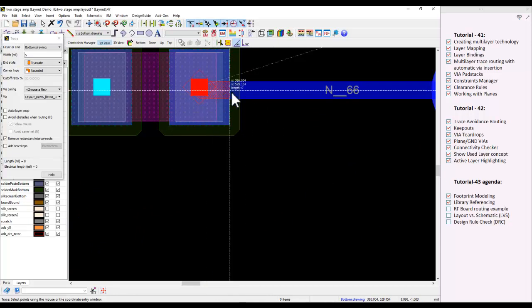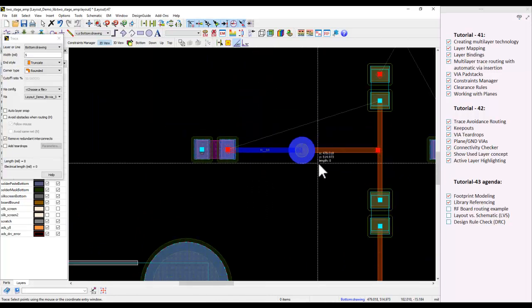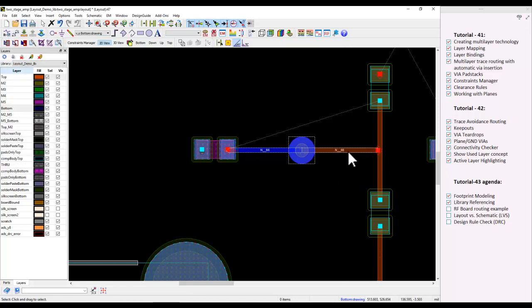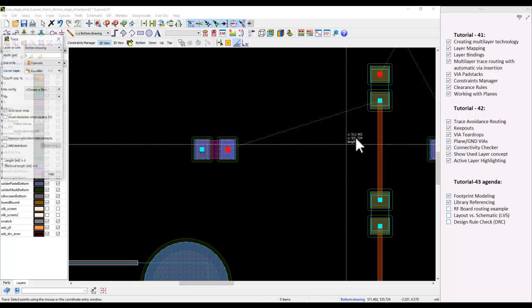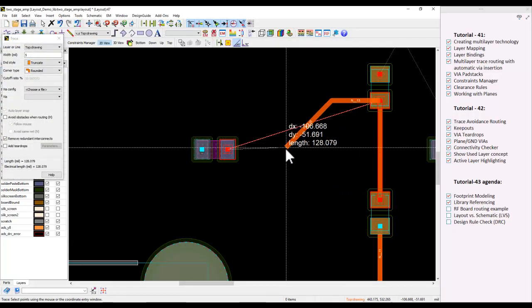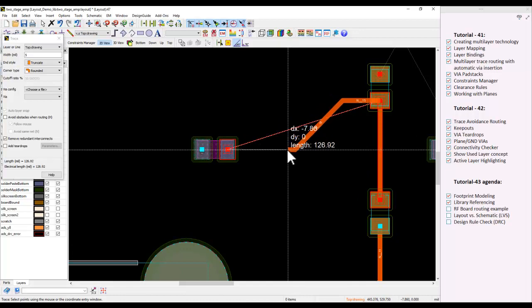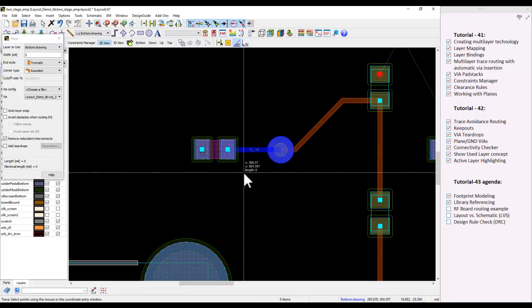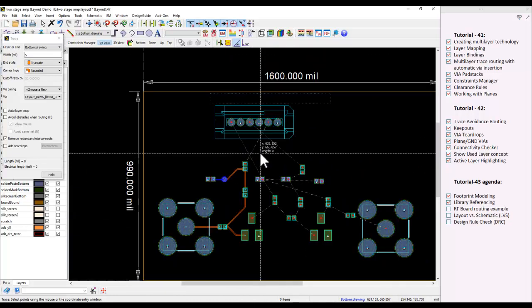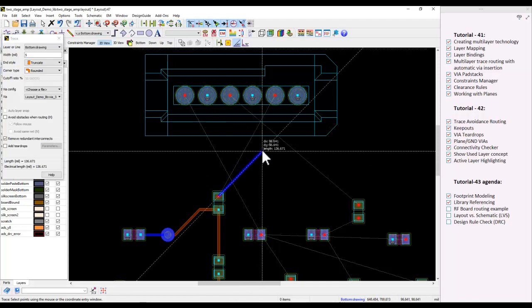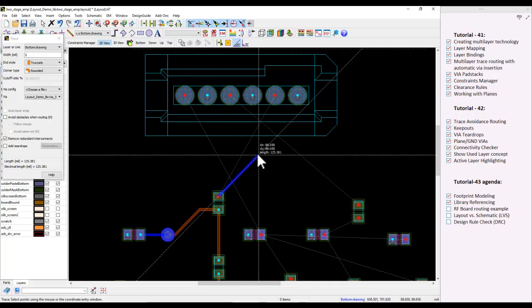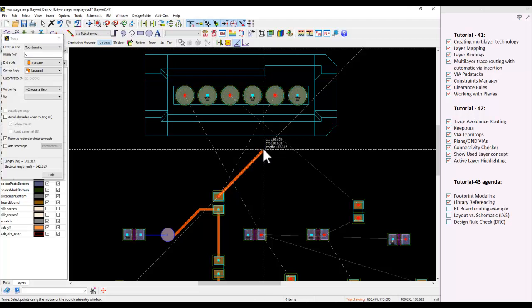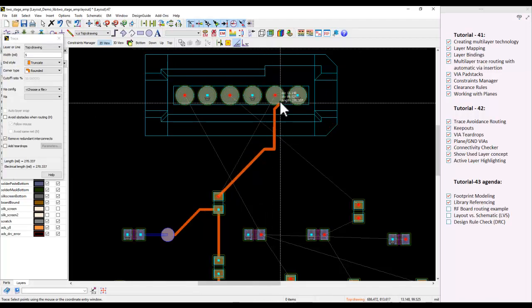And here now you have the connectivity to that trace, but here you can see it's complaining because it's not connected properly. So it's saying I want to connect to that guy. So that's fine. We can insert a new trace from there. And once we reach this point here, let me go to the bottom layer, and let's make a connection there. So now everything is fine. Similarly, while going to this connector, I can route myself from the top layer. And from here, let's go ahead and join.